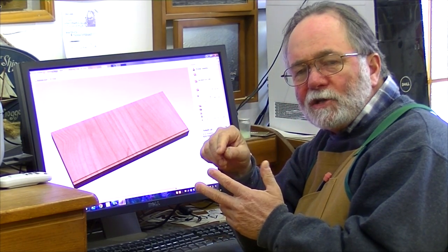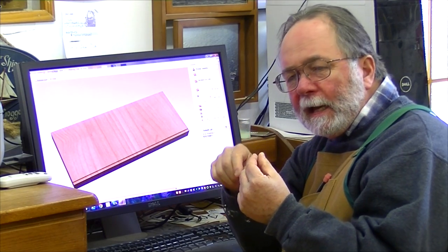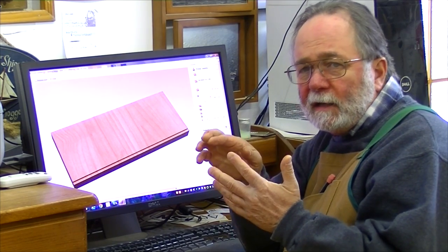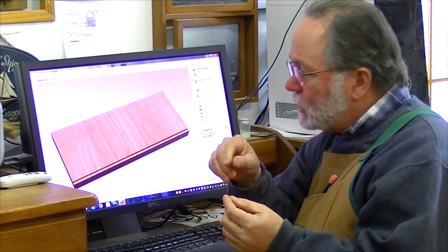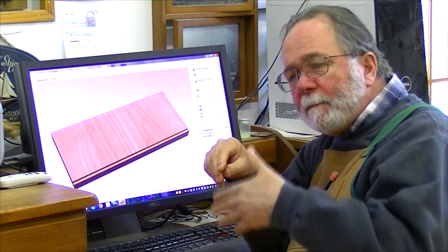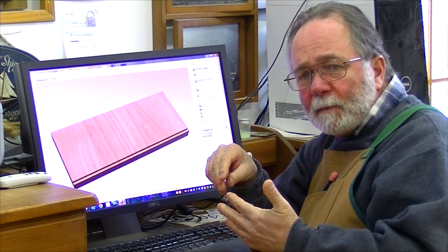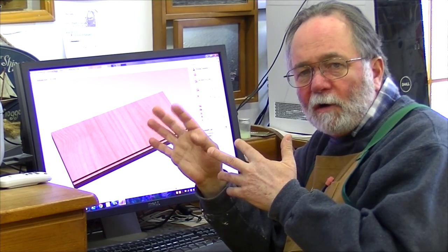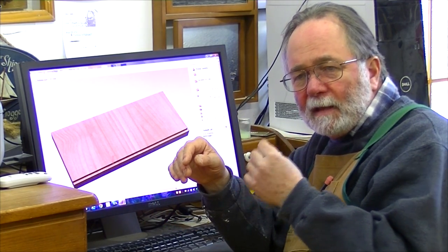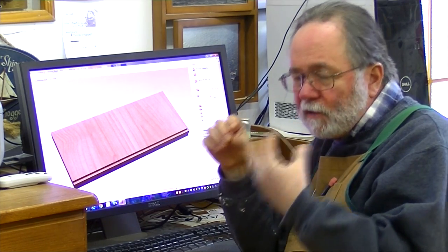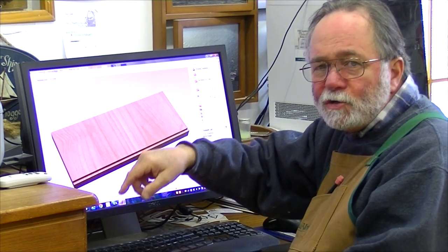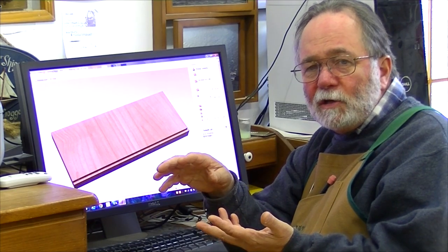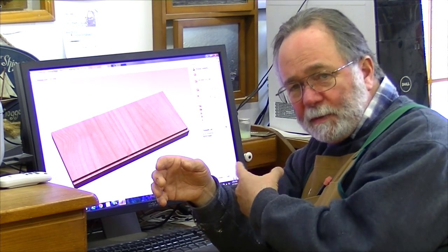The advantage of that is the tapered ball nose bit has a flute that goes way up the side of the bit. And so that flute can be cutting the entire time if you let it. Instead of just using the very tip of the ball nose, I'm going to actually use part of the side of the flute and take very light passes, 10% or so of the bit's diameter. That is of the 16th inch bit's diameter, so these are very tiny passes. I'm not putting undue strain on the bit, and yet I'm making the same cut, and I can completely eliminate using a rough cutting bit on this piece.